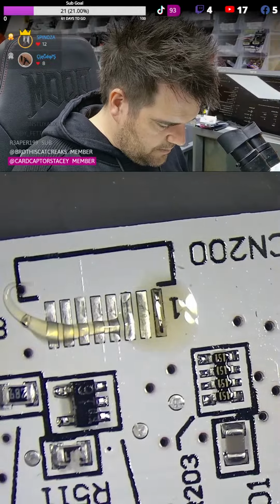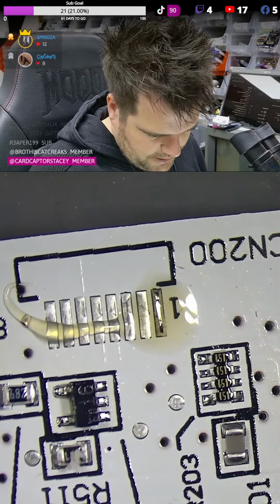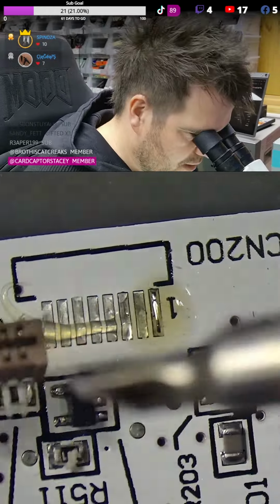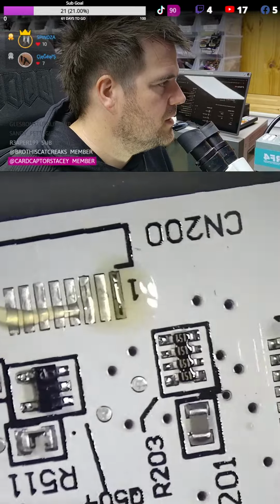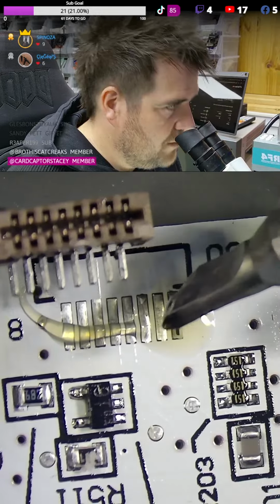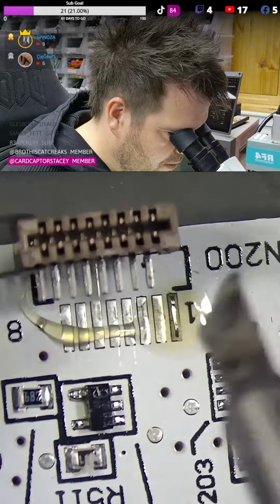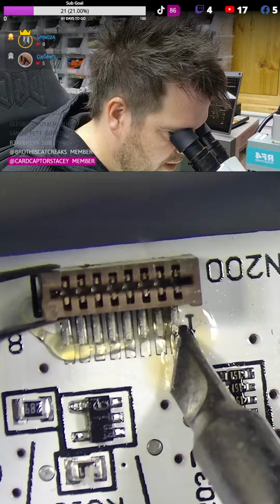You don't want to melt the plastic, so basically, watch where you're soldering and pre-plan. So I don't want to melt this connector on this side. So you can see we've got a connector over here I don't want to melt. And we don't want to touch the iron with this one. So just be very aware of where you're positioning your iron. When this comes in, it's going to almost touch that tip. So I almost want to be down here. And then warm that pad up, place the connector on.